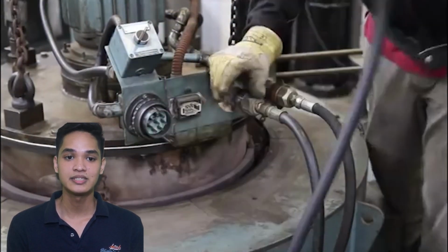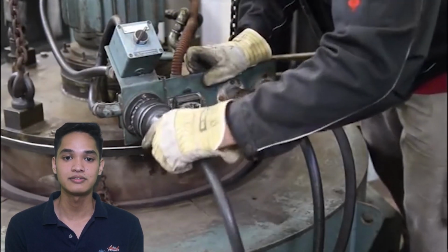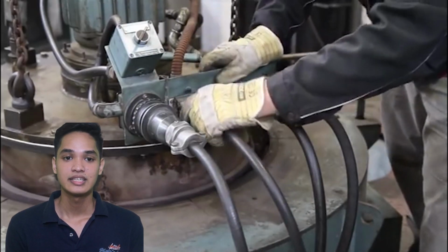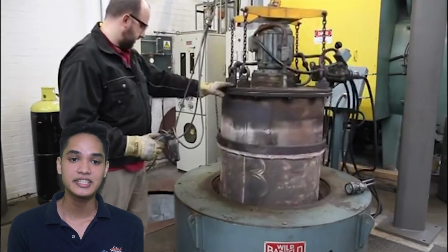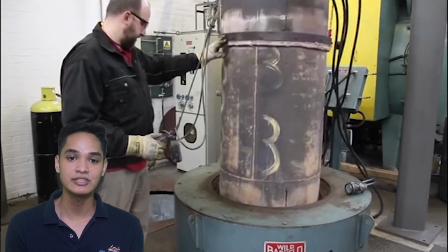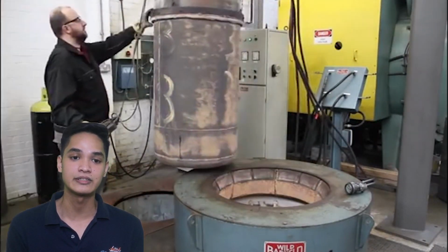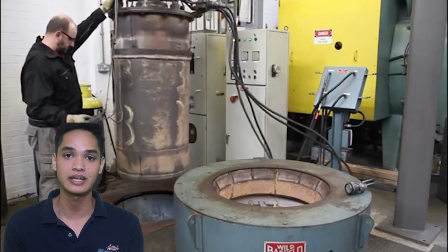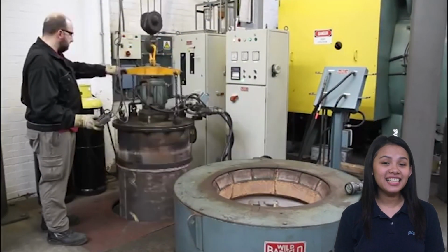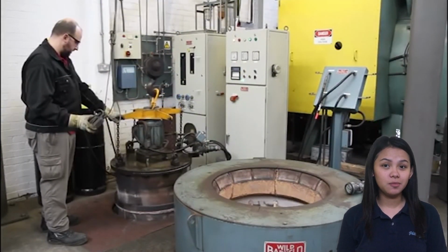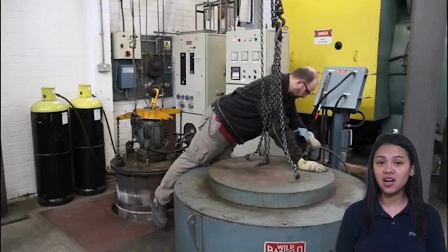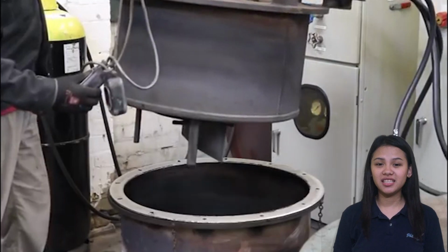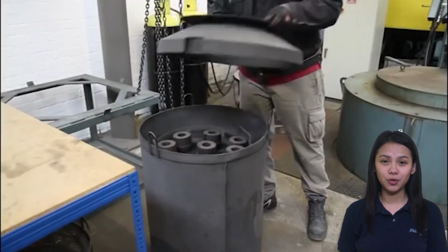The iron nitride is dispersed in minute particles at the surface and works inward. The depth of penetration depends on the length of the treatment. In nitriding, soaking periods as long as 72 hours are frequently required to produce the desired thickness of case. Nitriding can be accomplished with a minimum of distortion because of the low temperature at which parts are case hardened and because no quenching is required after the exposure to the ammonia gas.